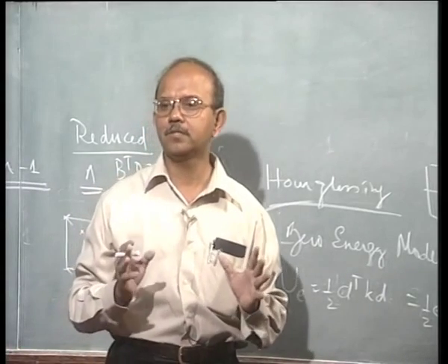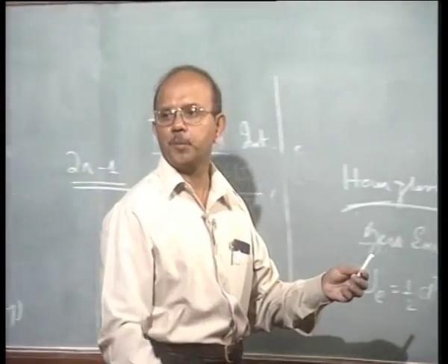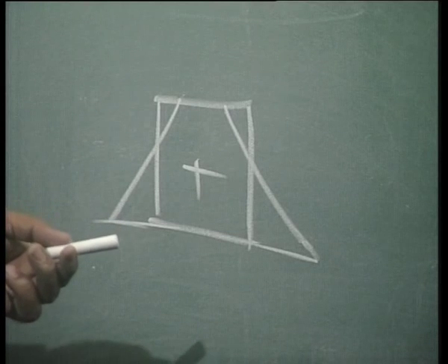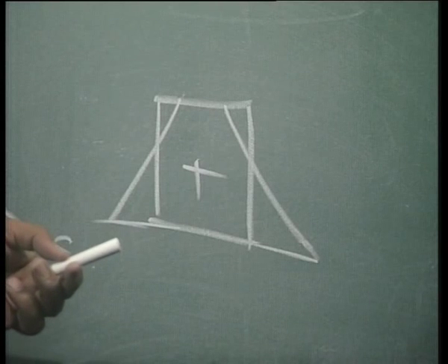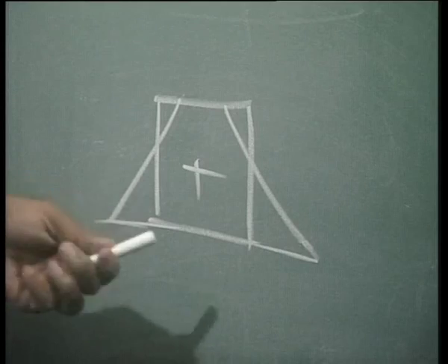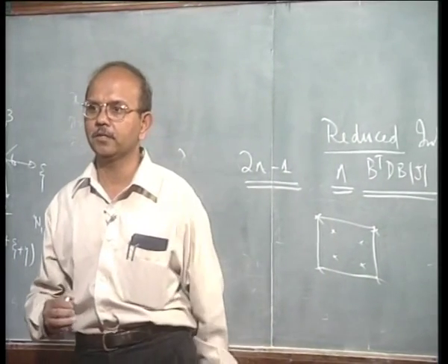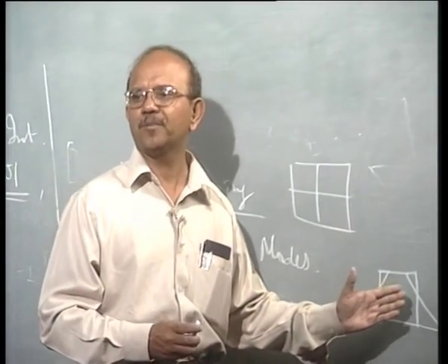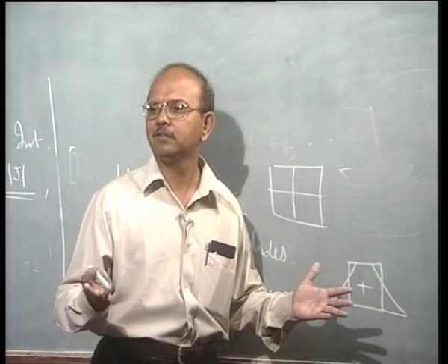One of the select locations is my Gauss point, the center of the element, because I am using the 1/1 Gauss point. So though there is strain in this element, my concentration being at this point gives me epsilon to be 0.